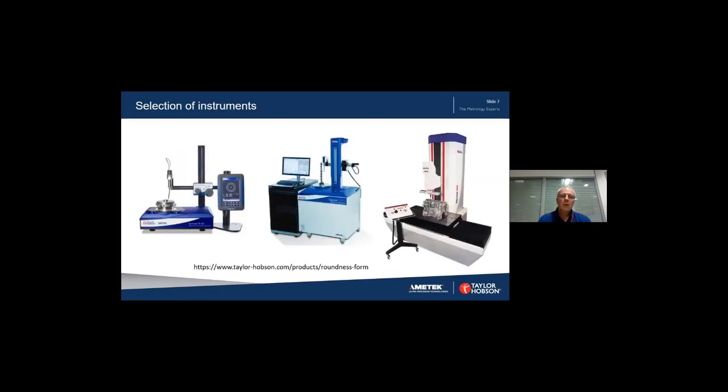Here are three different roundness instruments from Taylor Hobson. On the left is the Citronic roundness instrument, which is an example of a benchtop rotating workpiece instrument. This particular instrument is fully manual, as none of the axes are motorized. Nevertheless, it's an extremely accurate instrument using a high-precision air-bearing spindle. Although not covered in this presentation, the instrument's also capable of measuring flatness and some other parameters related to flatness and roundness.